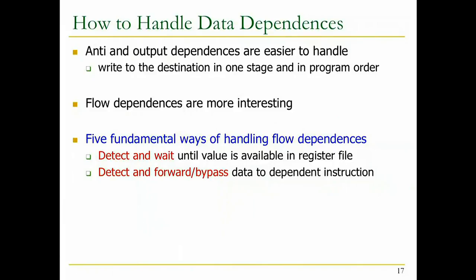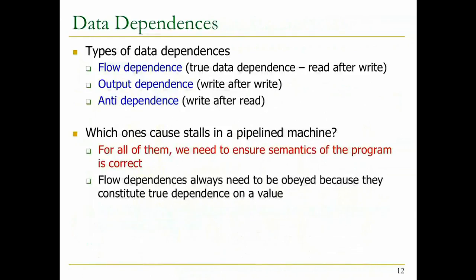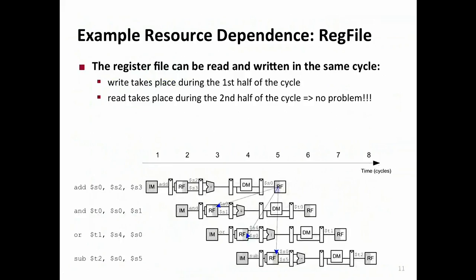Of course, in order to forward, you need to have a path from the end of the ALU to the register file stage. And you need to have a way of detecting that. Right? And that's not enough, because the instructions may not be sequential right after each other. The dependent instruction may be after that. Right? There might be one instruction in between, which is, if you go back to this picture. Oh, there should be a nicer way of going back. Okay, that's not that bad.